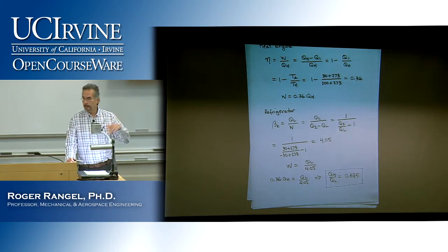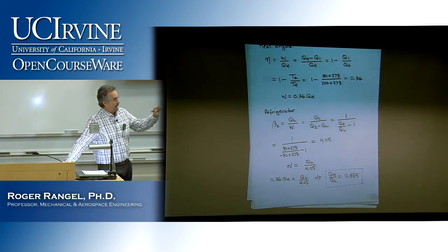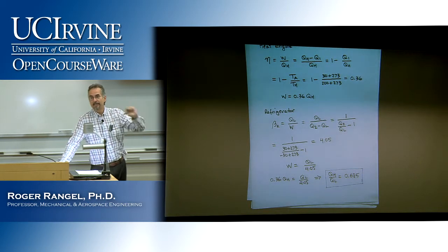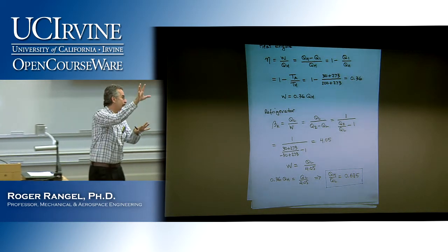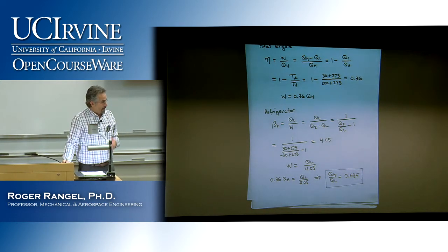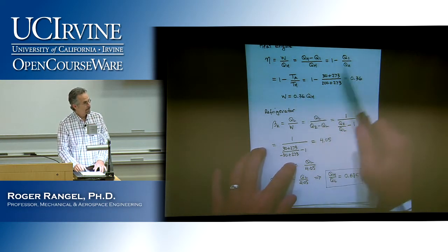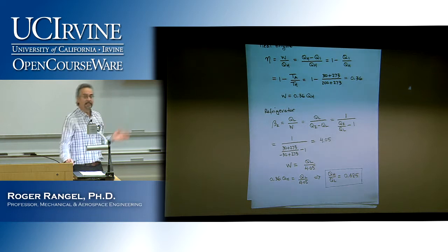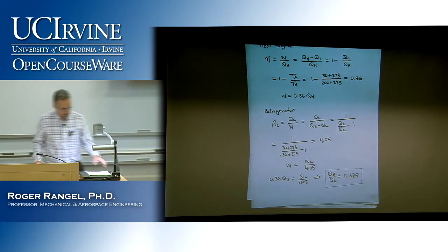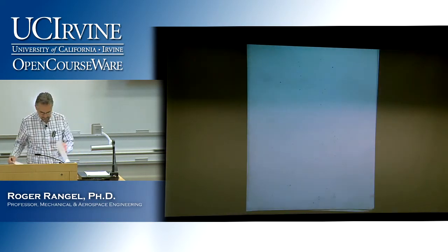I told you earlier that because of the Carnot proposition that says that the efficiency of a Carnot heat engine depends only on the temperature of the reservoir, the simplest relationship that we can find between the heat transfers and the temperatures is this, where we just take the ratio of the Q's is the ratio of the T's. But now we can formally do it by looking at the details of a Carnot cycle.